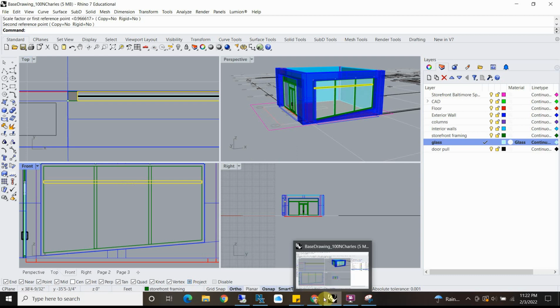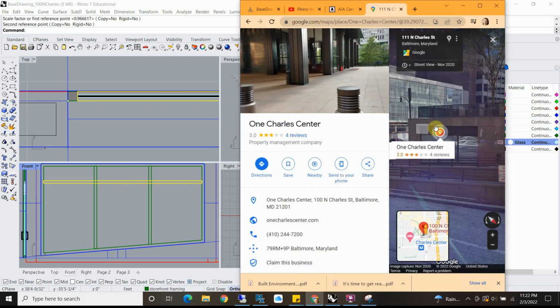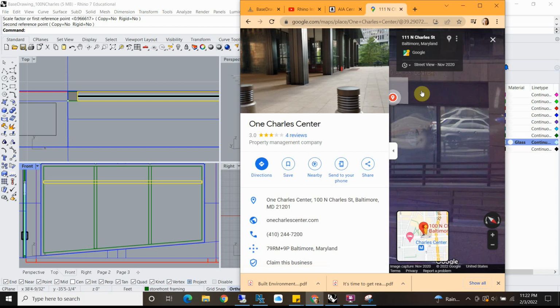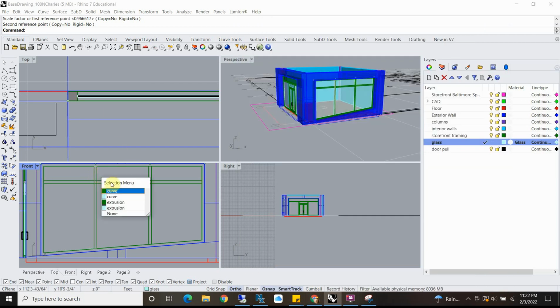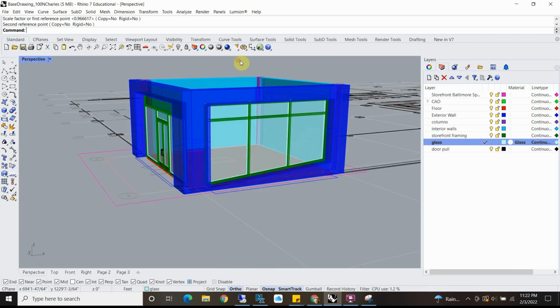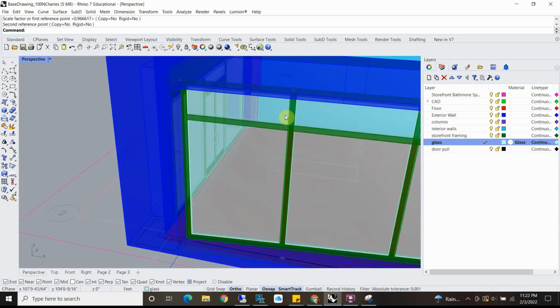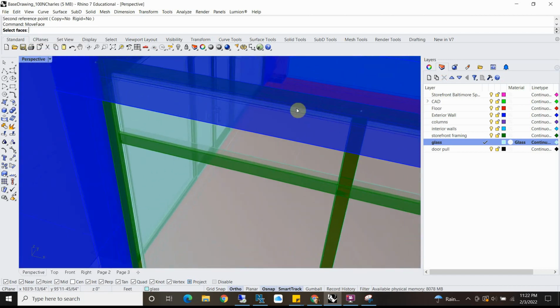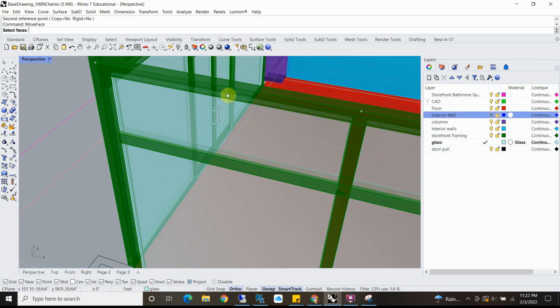Let's take a look at what our side elevation looks like again. So it looks like those don't want to go the whole way up. And then we're going to have a plate in there again. So we're going to use some move face to get that to happen. So I'm going to type in move face. I'm going to turn off the exterior wall a second.